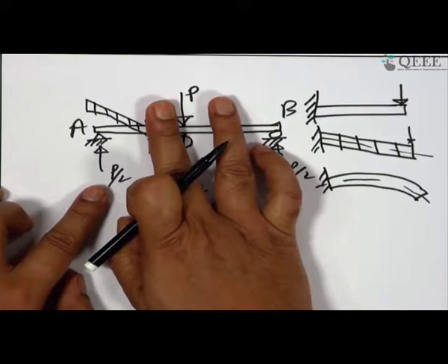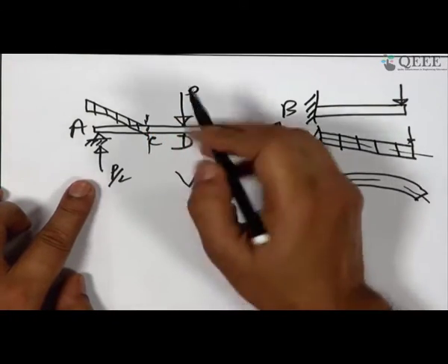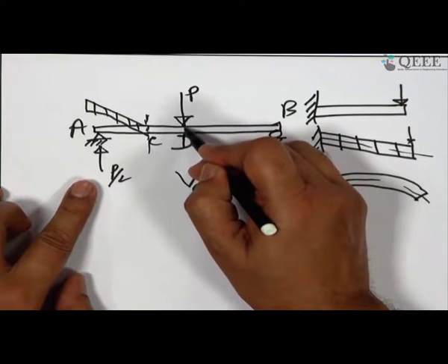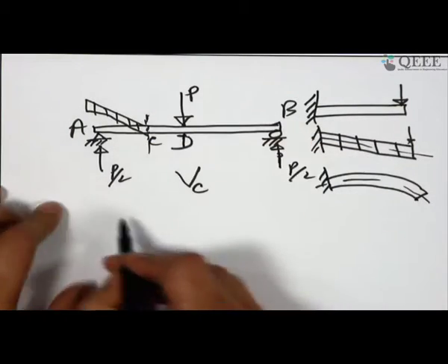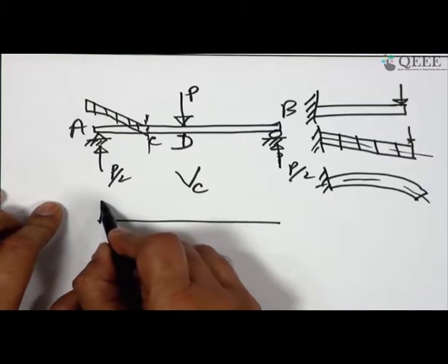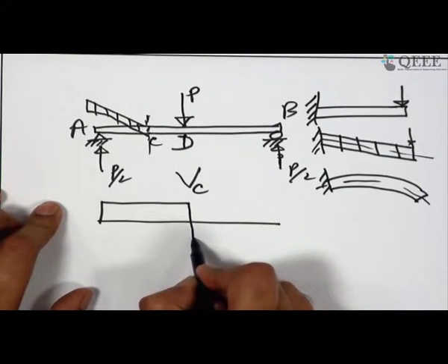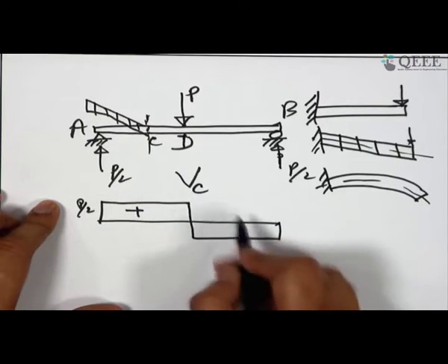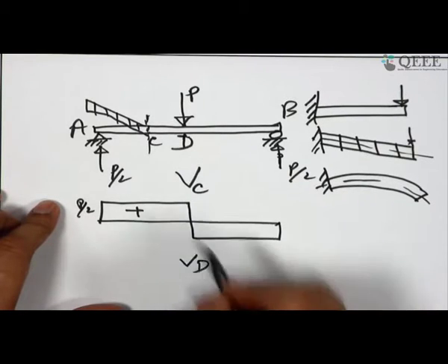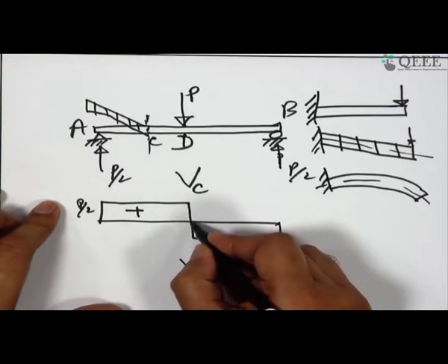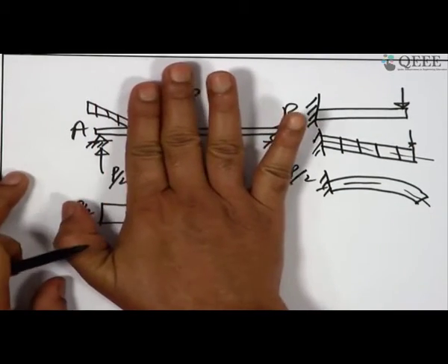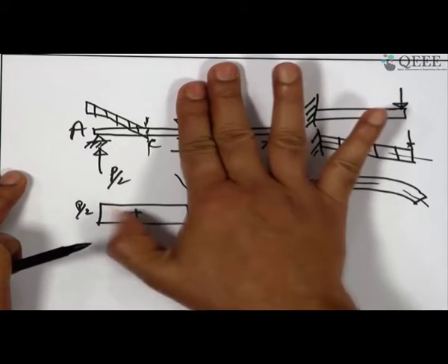Now, if this section is under consideration, sitting at this section, you do not actually touch the load and then consider it. And also there is one more thing. So, this is what is for the left hand shear and the right hand shear. Also consider this force. This will be very interesting to you, because you already know the shear force diagram. This is P by 2, it comes down by P total. So, this is P by 2, it is a positive shear according to us. So, if we consider the shear at D, then what is happening here, up to here you are coming from left. So, P by 2, P by 2, P by 2, always the shear is P by 2 here, you have drawn the diagram.